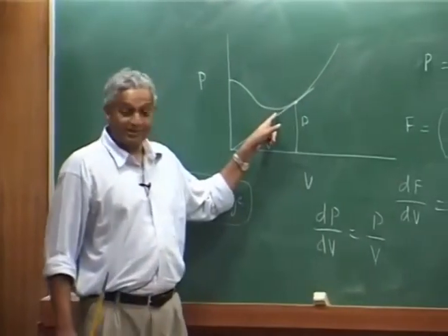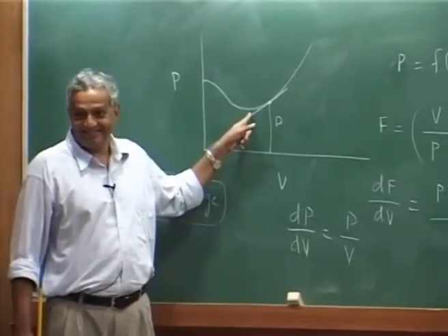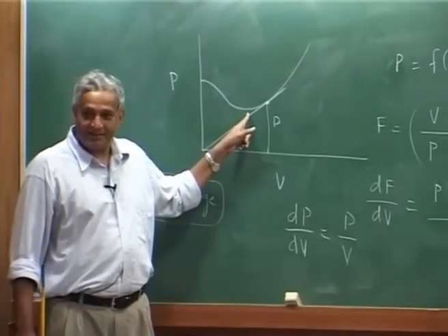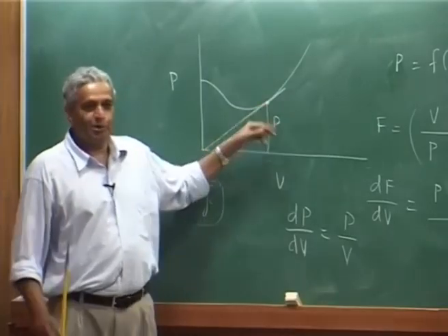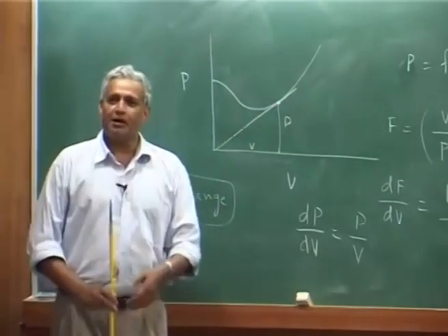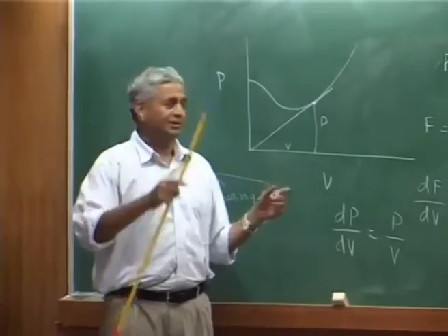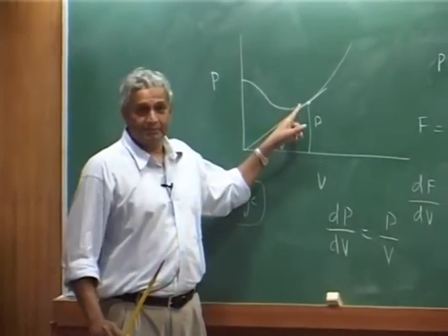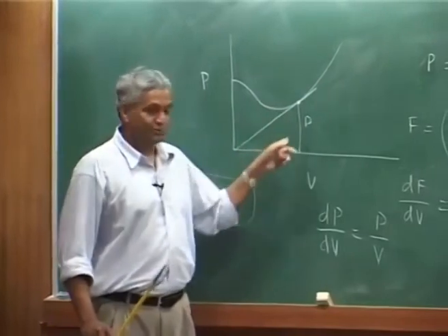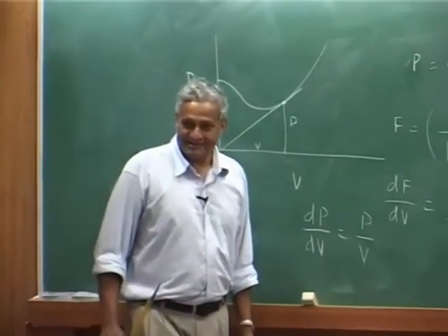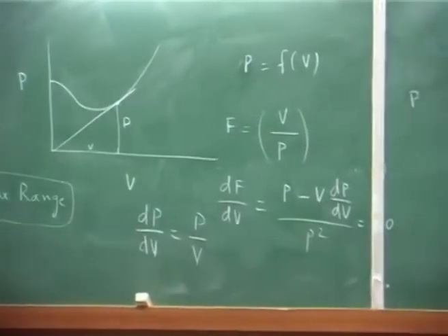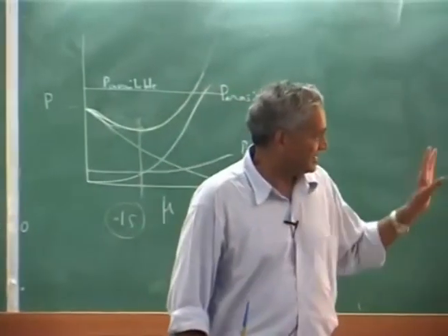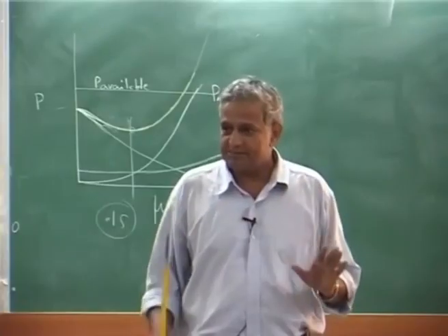Now, you do not fly at minimum power speed, you actually fly at a higher speed. So, if you want endurance, that is a long time, you want to float around, then you use minimum power, but if you want to increase the range, you do this. Okay. Then there is one more problem in this, which I will come to later.